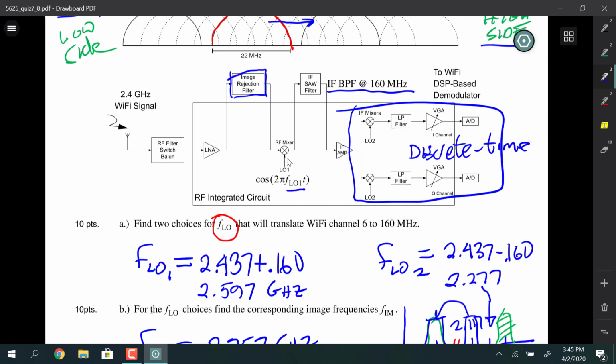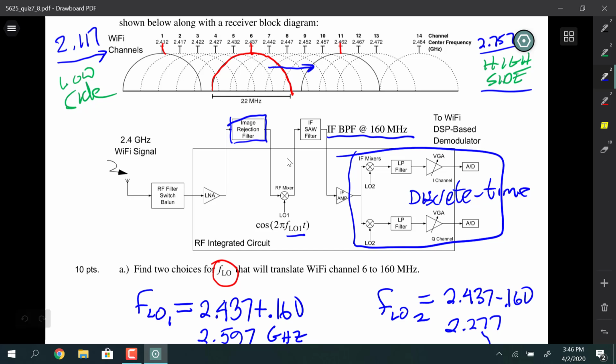However, here's a good however question. The low noise amplifier is not protected, so if the signal at the image frequency is very powerful, it could overload the LNA and make it difficult to receive our desired signal just because the LNA didn't have enough headroom to support a strong out-of-band signal.